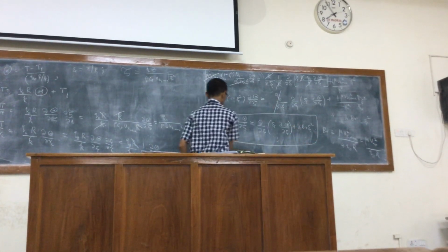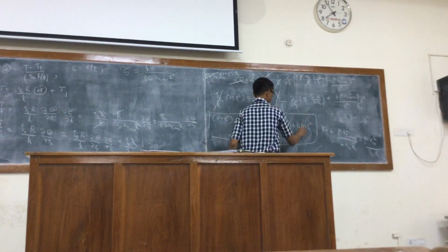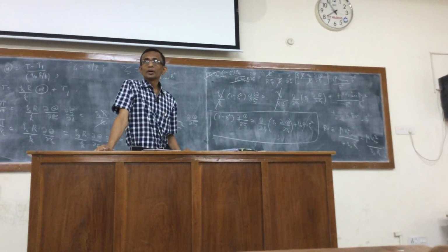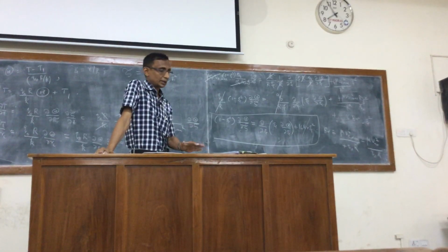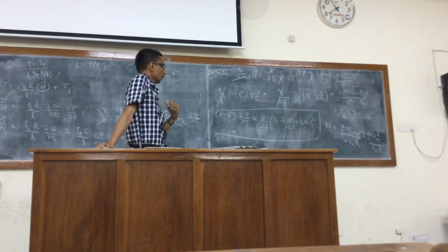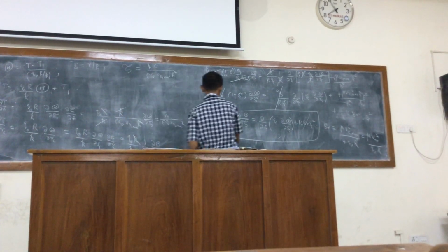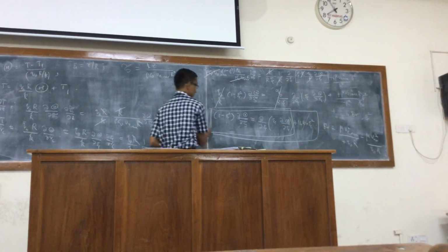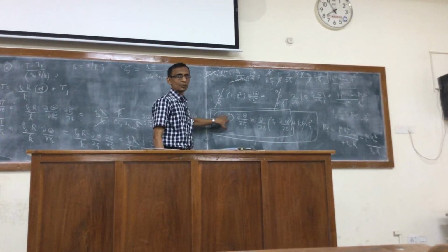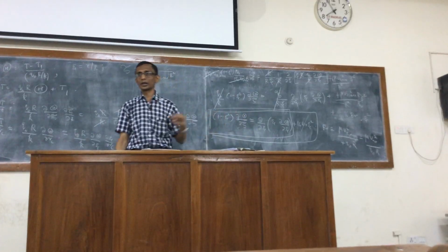And so now what he says, consider the case where the Brinkman number is very small, right? And we give some conditions. They have given some conditions where that would be justified. So if I do that, then I'm left with this solution of this equation. This is still complicated because of the presence of the 1 minus psi squared. Otherwise you can easily do it by straightforward separation of variables, right?